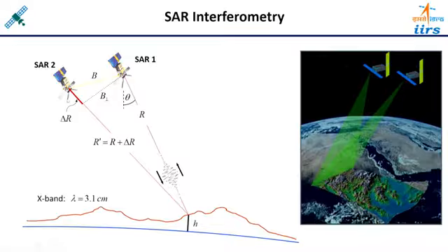So using trigonometry, we can calculate this height parameter very easily. This height parameter is nothing but the topography of the Earth surface. So you can say the topography can be mapped using two SAR images, by generating an interferogram, or by calculating the phase difference of both the signals, the height can be calculated. The popular application of height is DEM generation. So SAR based DEM generation is also possible. So this is the SAR application for topographic mapping.